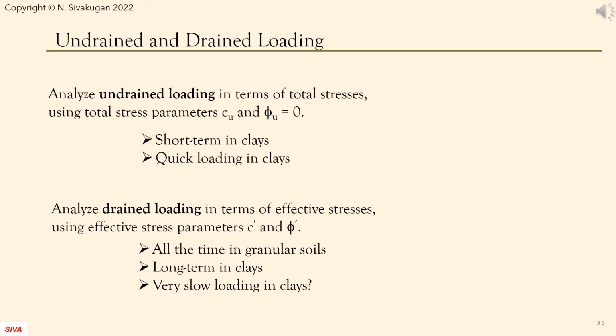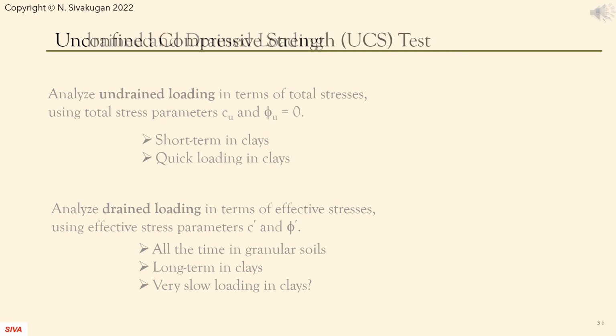In clays, undrained loading is assumed during the very early stages of loading or when the loading is quick. These may be analyzed using total stress parameters, Cu, and phi-u equals 0. In clays, long time since loading or during very slow loading, drained conditions are assumed, and the analysis is usually in terms of the effective stress parameters, C' and phi'.